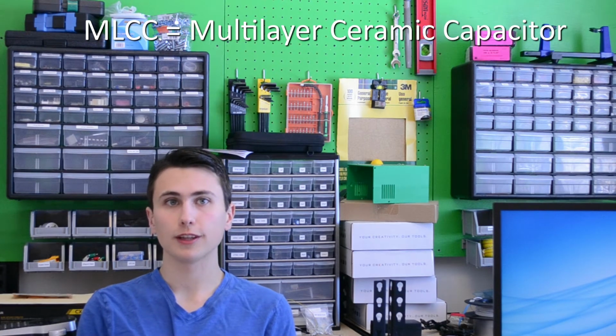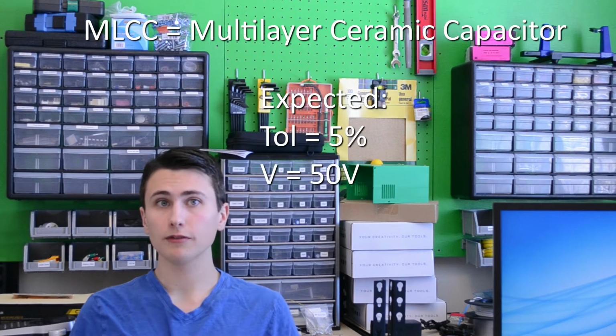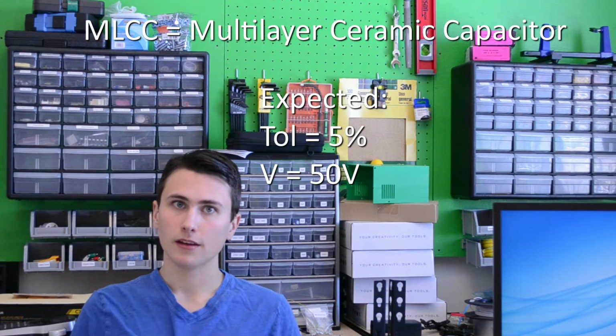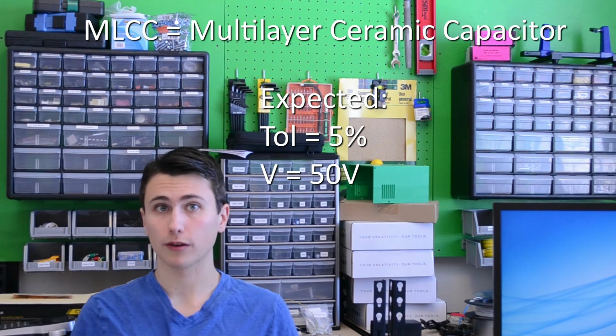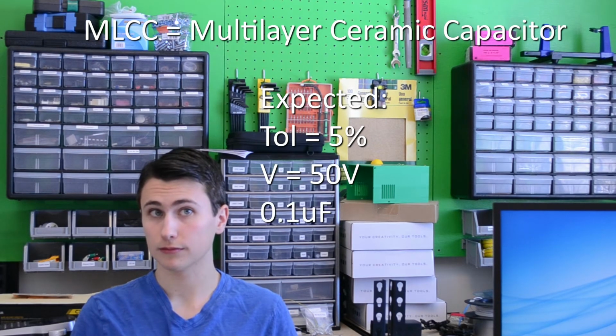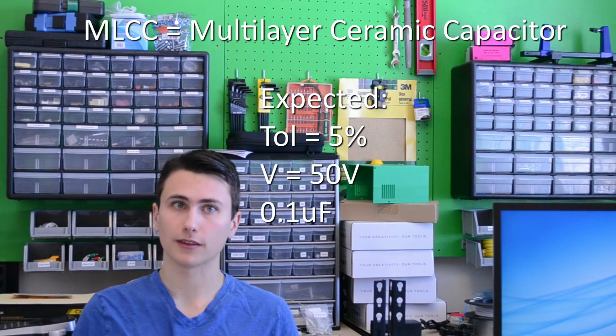A ceramic capacitor like this could typically have a tolerance of around 5%, and a voltage range of 50 volts without getting too fancy. A part like this in an 0805 package could have a value of 0.1 microfarads without getting too expensive. Now let's compare this 0.1 microfarad capacitor to the 100 microfarad capacitor.